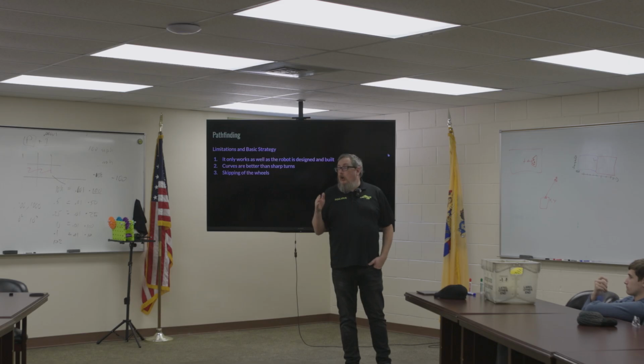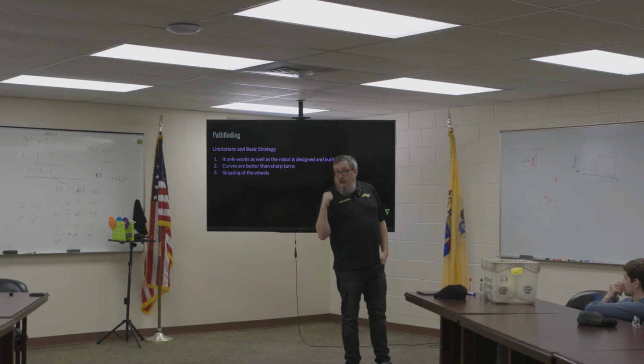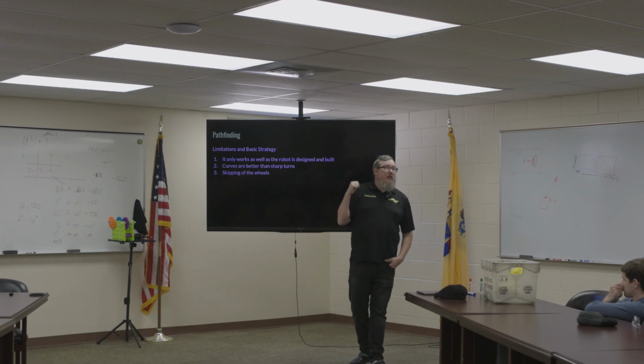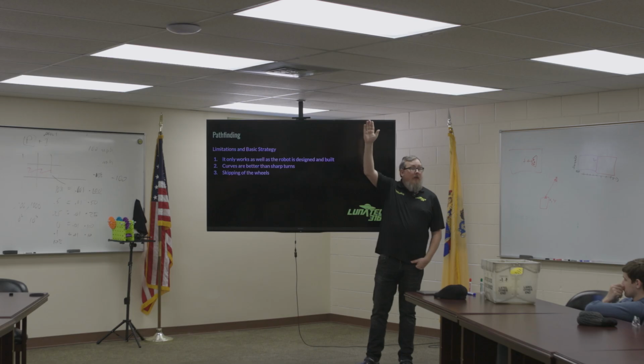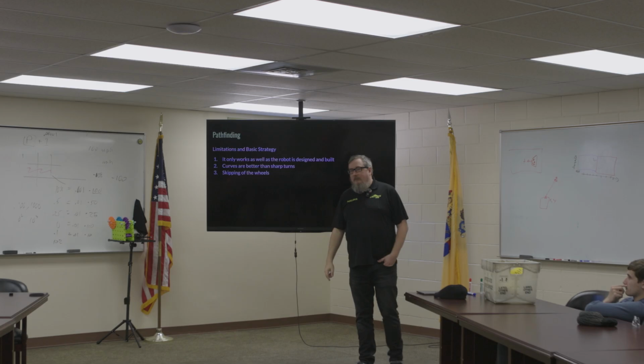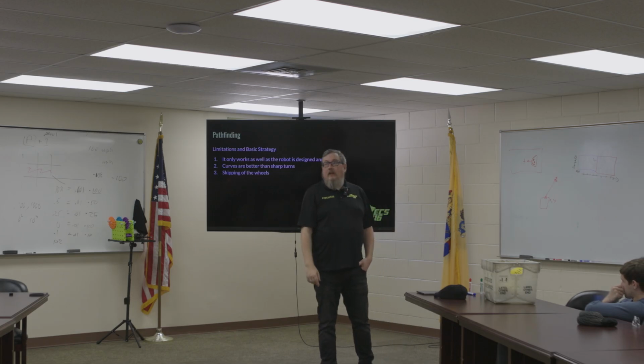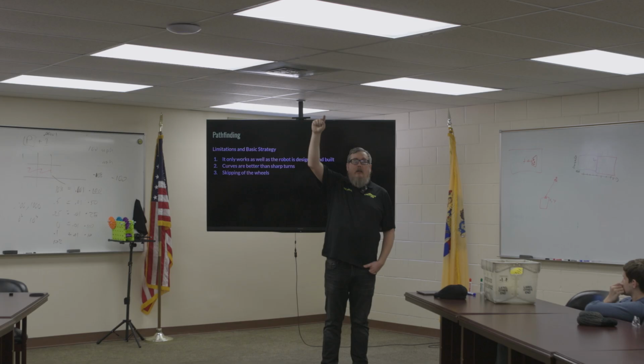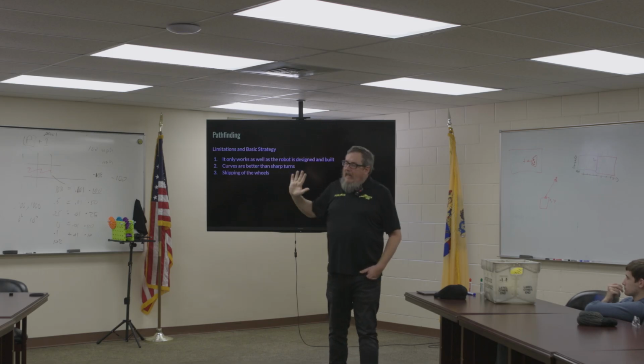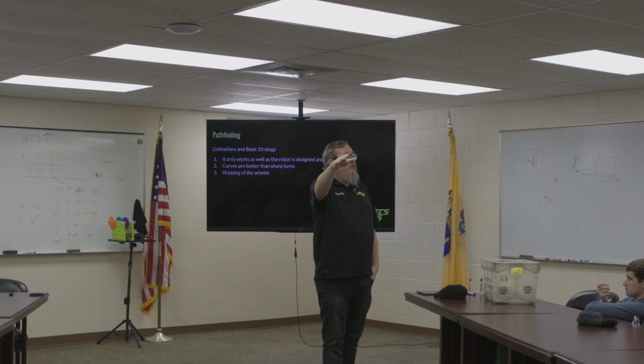Pathfinder and path planning only works if we have a well-built robot. You notice how the robot kind of did a little wobbly thing at the end? Yeah. One of the limitations for us in pathfinding this year was we couldn't lift the elevator up as we were driving. Why was that? Because the weight on the top of it will make it wobble back and forth to a point where we could tip over. Exactly. There were teams that once they got the coral in at the player station, they lifted their elevator to the top position and came into the reef at full speed to deliver it.